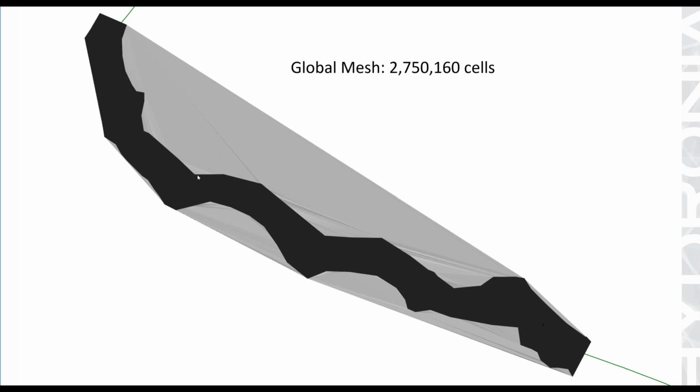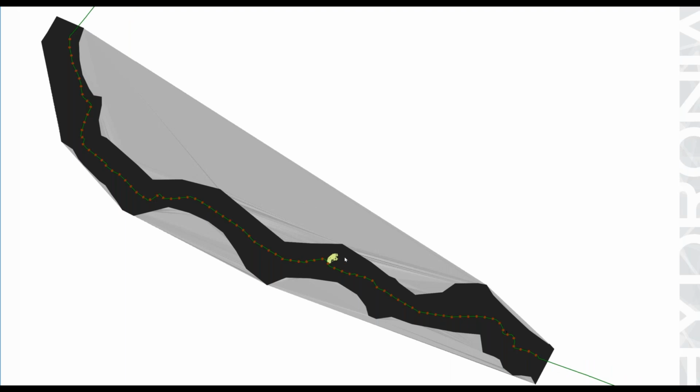Now, what was the problem with that is that the mesh needs to be copied to each of the spills, because each spill would use the same whole mesh, even if the spill is very small, as in this case. You can see here, one single spill only impacts a few cells very close to it, but still needed the whole mesh, which generated a lot of unnecessary overhead.